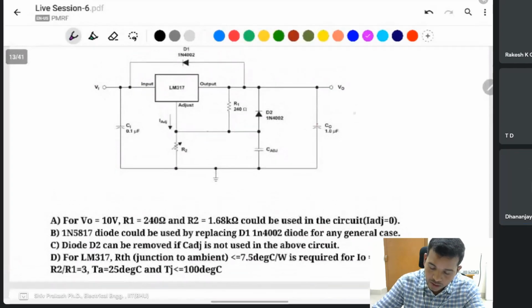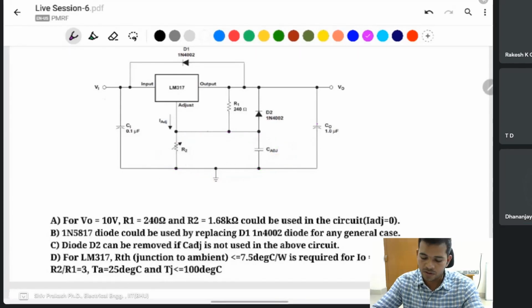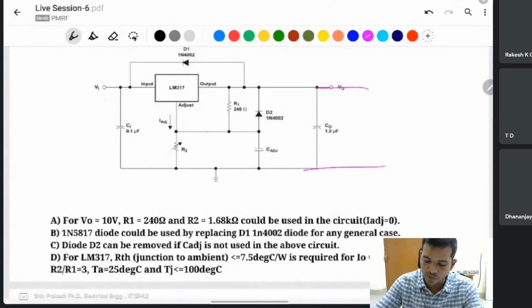Is it about the RC time constant, sir? The bottom capacitor and the rest. What is C2? It is used for filtering, to make the voltage constant and reduce ripple. Already you have reduced the ripple with the output capacitor.